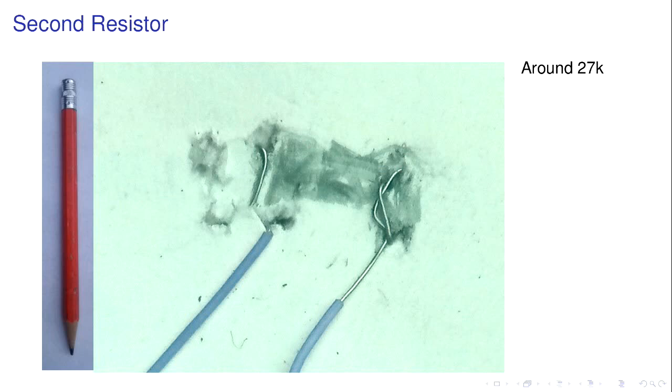And it seemed to have reasonable properties except for vibration. Every time you wiggled the wires, the resistance would change. We need a better way to attach wires to graphite or other substances. It's really mechanically unstable. So what are we going to do? Well, I've tried mechanical, it shakes loose.